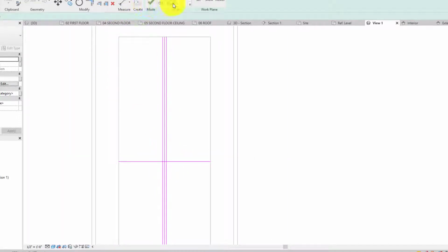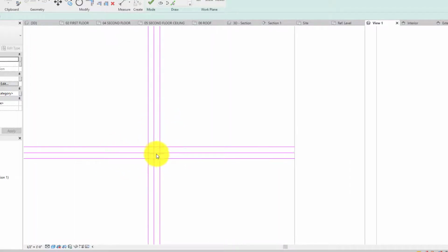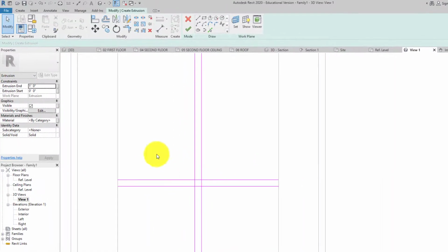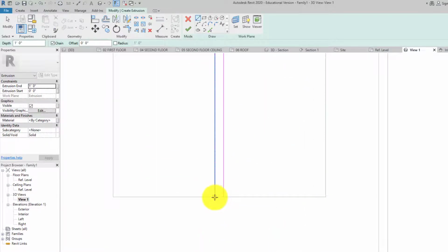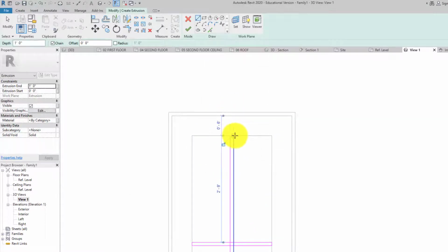I'm going to do the same thing for this line down here in the middle. I'm going to do 0.5. So I'm going to do half an inch on the bottom, half an inch on the top, and now I have three horizontal lines and three vertical lines. I'm going to go ahead and delete the middle line of both. Grab a line tool, just a regular line, connect those two, connect these two, connect these two, and connect the top two.